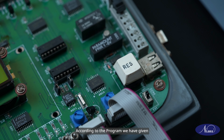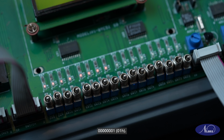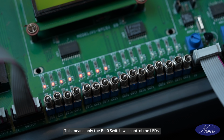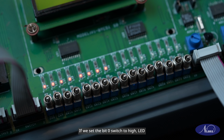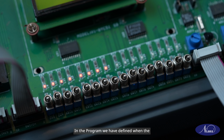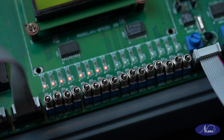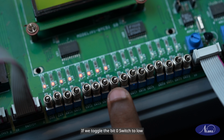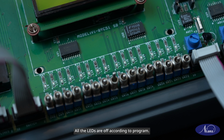According to the program, we have given 00000001H. This means only the bit 0 switch will control the LEDs and other switches will not be controlling the LEDs. If we set the bit 0 switch to high, the LED will be blinking according to the program. In the program, we have defined when the switch is high, the LEDs will be in FF and 00 with a delay. If we toggle the bit 0 switch to low, we can see there is a change in the output LED. All the LEDs are off according to the program.